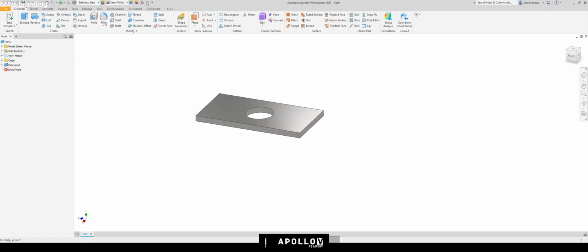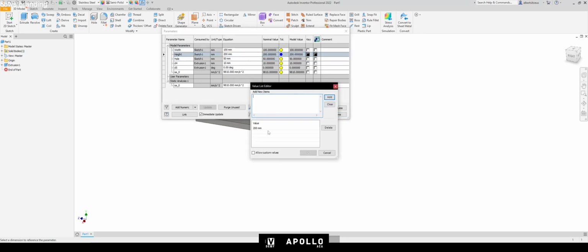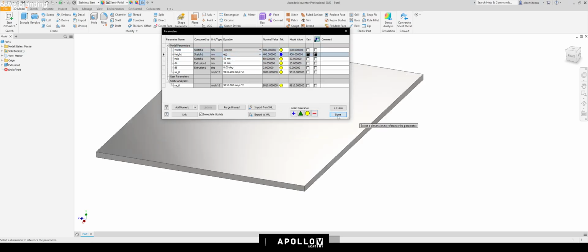And finally, that is basically it. If I just go over to this little FX area, you'll see that we have the ability to drive our height. And if I right click and say multi-value, I got 30 seconds left to show you something else. So I can just go 100, enter, 200, enter, 300, enter, 400, enter, 500, enter, say add. Okay, right click over here, multi-value, 300, enter, got 10 seconds, 500, add, say okay. And in this case here, pick on the list, boom, boom, done and dusted.